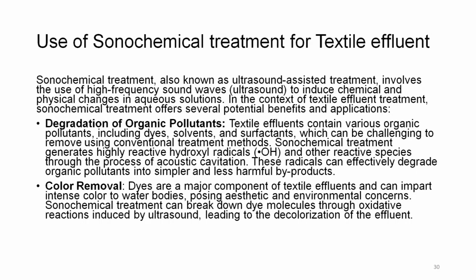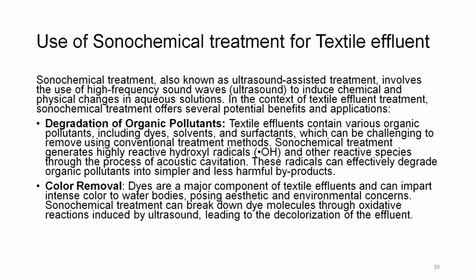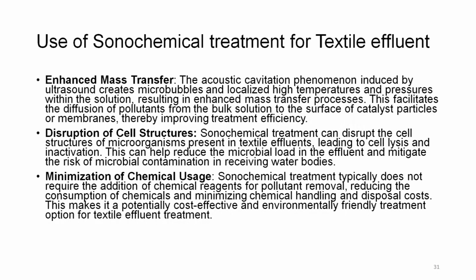Color removal. Dyes are a major component of textile effluent and can impart intense color to water bodies, posing aesthetic and environmental concerns. And this we have seen time and again. Whenever we talk about color removal, we talk about this. Sonochemical treatment can break down dye molecules through oxidative reactions induced by the ultrasound, leading to the decolorization of the effluent.